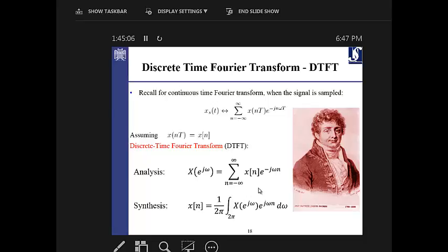So a spectrogram is actually three-dimensional. It has time, frequency, and intensity. We say spectrum, and spectrum is only the frequency domain. It doesn't care about the time domain at all. So when you say the spectrum of the signal, it means that, for example, you take the entire signal and study the entire frequency components that might be contained inside that signal. You don't care about moving over the time frames. But a spectrogram is a multi-resolution analysis which tells you how the spectrum is varying over time. It's different from spectrum. So you have the spectrum, and you have a spectrogram.